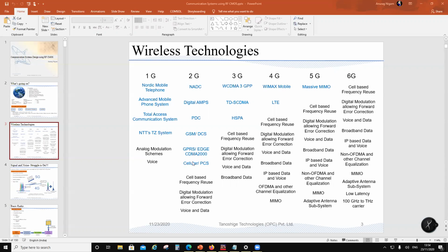So if you are in the 800 or 900 megahertz range, this would be called cellular. If you are in the 1900 megahertz range, it will be called PCS, right? So we had CDMA under 2G. We could do data transmission, we could do voice and all that. So these are all phone standards, right? What was realized is that the channel bandwidth is only about 1.25 megahertz, so basically your throughput is limited to that. So they realized that we need more channels now.